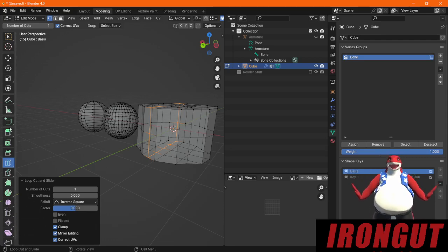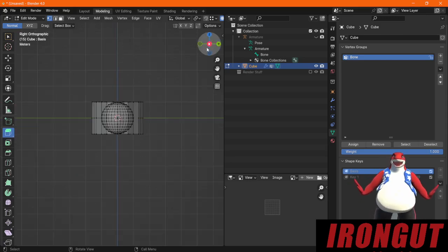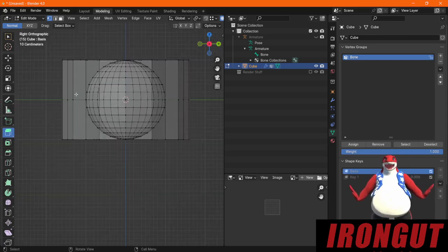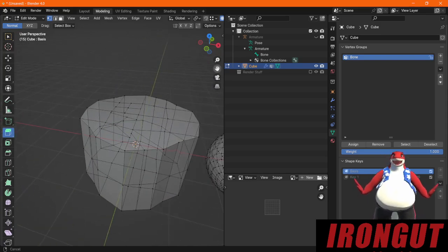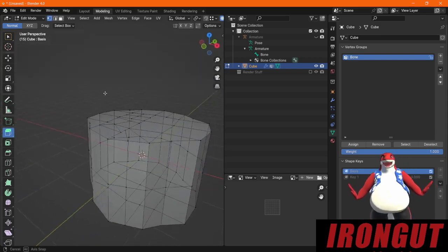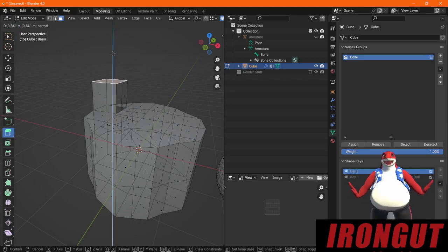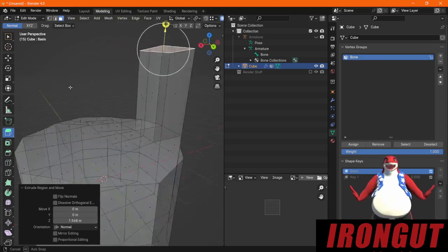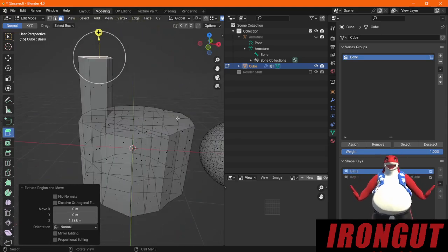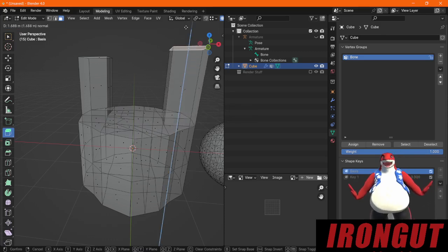And like, here's the extrude tool, which is one of my favorites to use. This is good for when it comes time to make a new limb or something, an antenna, anything that's going to stick out. You would select the polygon that you want to make stick out, and using the extrude tool, bam, it's just that easy to make something stick out. Just highlight it, grab it, and up you go.